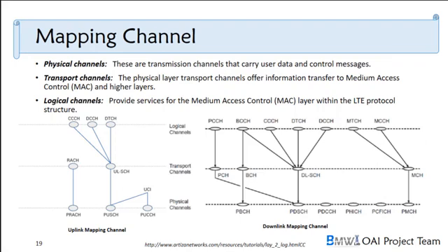The PHICH will transmit the ACK and NACK, and the PCFICH will indicate the PDCCH of the DCI.